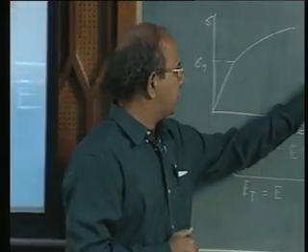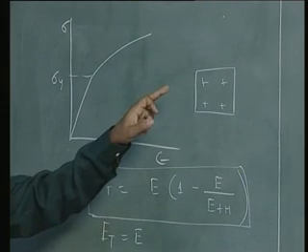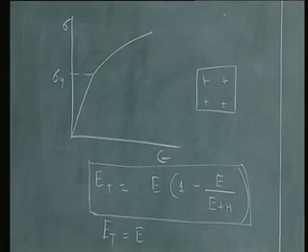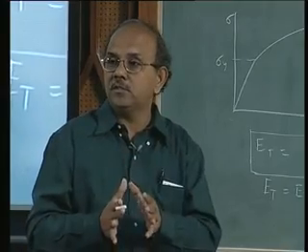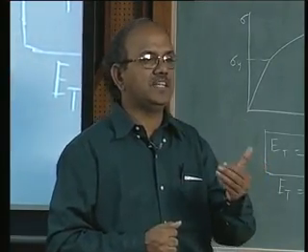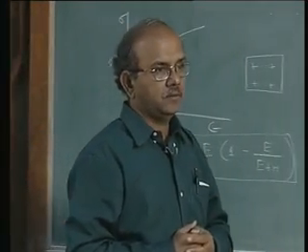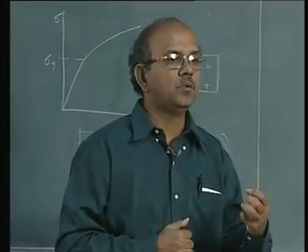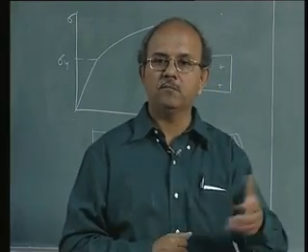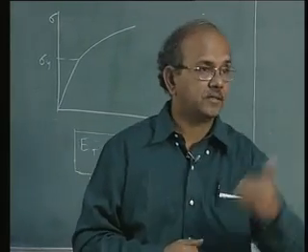So, if I use 4, then I will have 4 different arrays per element of history dependent variables stored. One of them can be called a yield switch. One of them will store the plastic strains. One of them will store the yield strength and so on.